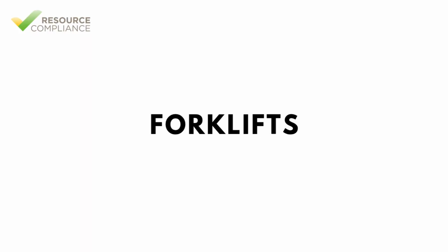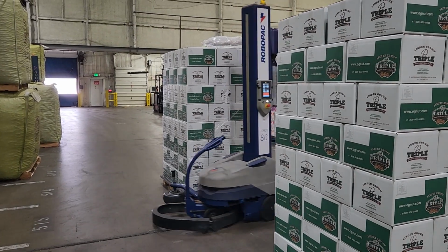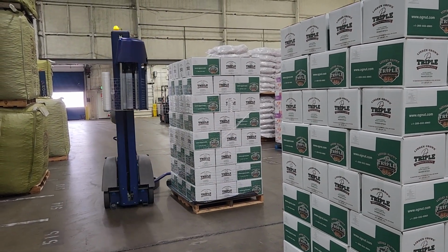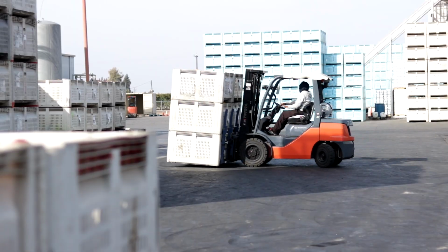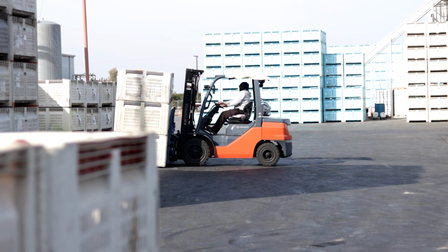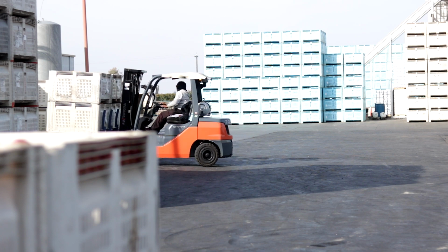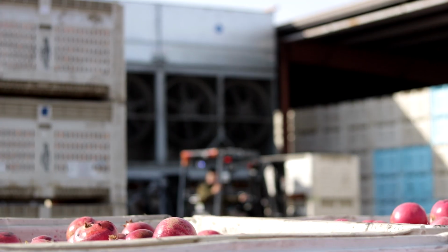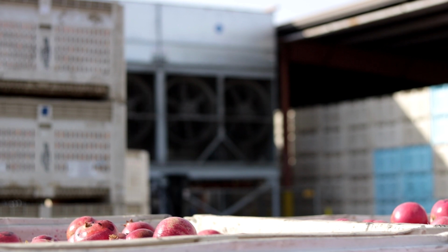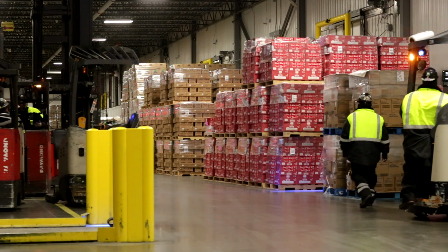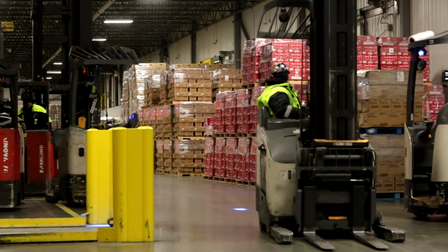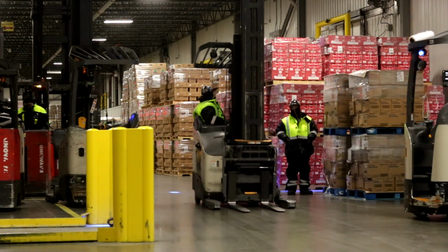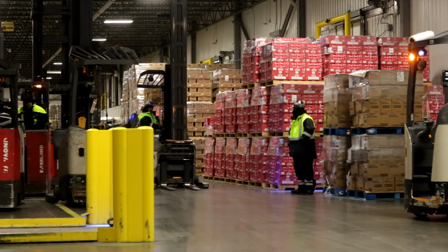Forklifts are one of the leading causes of workplace injuries in industrial settings. As a refrigeration technician, the best protection is constant awareness of forklift traffic, especially when entering or exiting rooms. Pause, look, and confirm that it's safe before stepping into a new area. Safety vests or bright clothing are helpful to make you more noticeable in dim or obstructed areas. Never walk directly behind or beside a moving forklift and maintain a safe distance when they are operating. Never assume a forklift driver sees you. Establish visual contact before crossing paths.